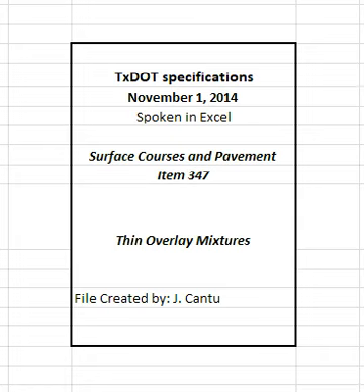JMF1 is the original laboratory mixture design used to produce the trial batch. When WMA is used, JMF1 may be designed and submitted to the engineer without including the WMA additive. When WMA is used, document the additive or process used and recommended rate on the JMF1 submittal. The engineer and the contractor will verify JMF1 based on plant-produced mixture from the trial batch unless otherwise approved.